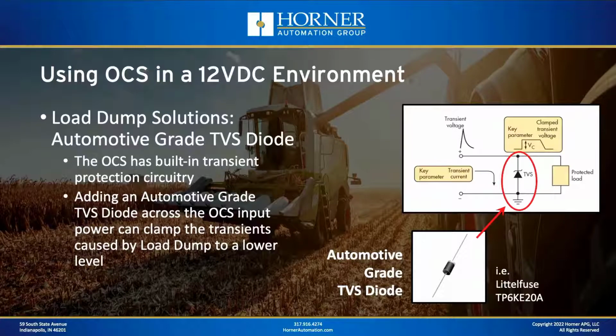Now, where can you find an automotive grade TVS diode? Well, you can find it pretty much at any electronic supply store like DigiKey, for instance. I think I picked up the Littelfuse TP6KE20A as being a good potential choice. It is a component that has leads. It's not surface mount, so you'll be able to integrate it in a control system, and it will provide the extra protection needed against some of those worst case scenarios with load dump.